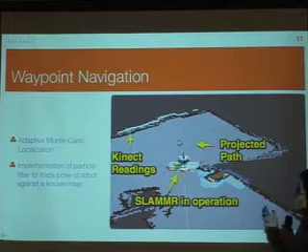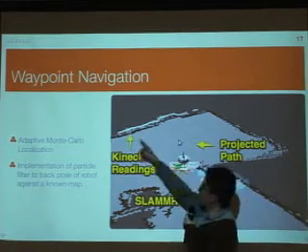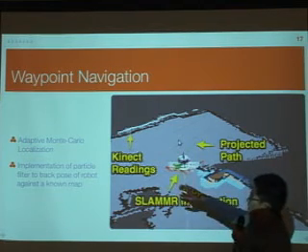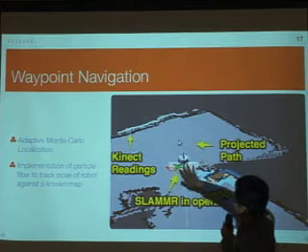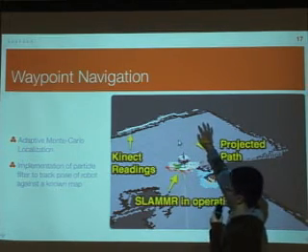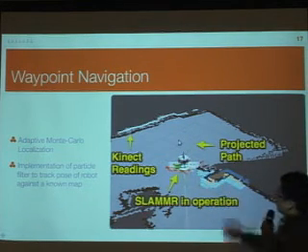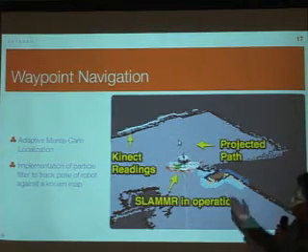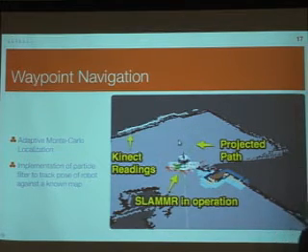And then once we have the estimation of where the robot is compared to the actual scan of the Kinect readings, we could generate this path to move the robot from the original place, which is somewhere here, to the destination. You can see the little green lines is the path that it generated, and also it has an obstacle. We implemented obstacle avoidance.